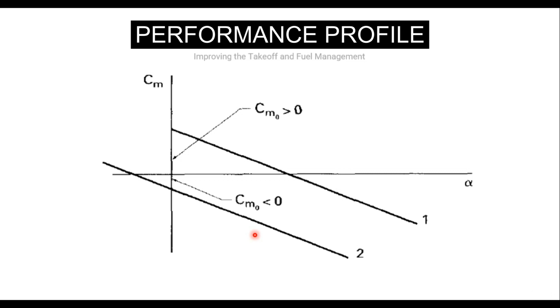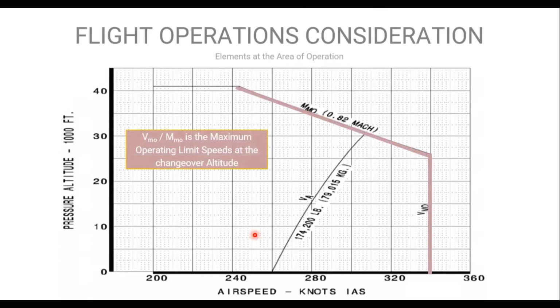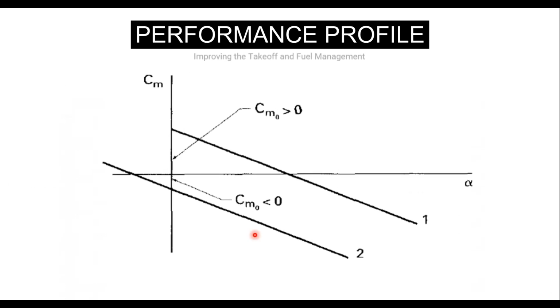Okay, guys, this is something the people working in flight operations will relate to very much, and the people in flight school will too. Whenever I increase the moment coefficient towards the negative part with the angle of attack, that means better stability for the aircraft. That means that whenever I move the CG of the aircraft forward, the aircraft stability will be better.